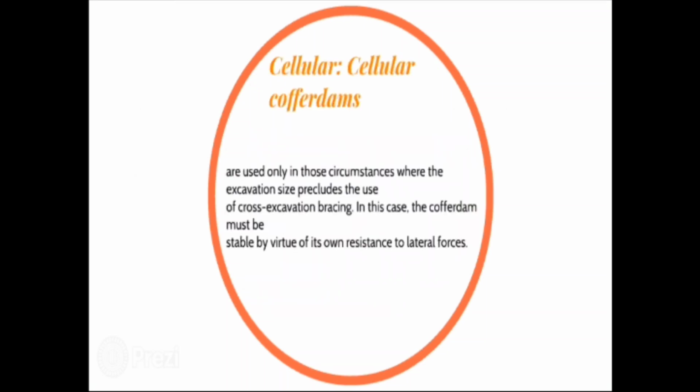The fourth one is cellular cofferdams. It is used only in those circumstances where the excavation size precludes the use of cross-excavation bracing. In this case, the cofferdam must be stable by virtue of its own resistance to lateral forces.